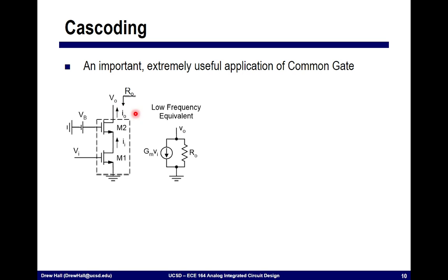Essentially we can take this amplifier, and we know M1 is inverting our input signal and generating relatively high gain. The current that's coming out of M1 is being buffered by M2. And here we're creating a much, much larger output impedance, or an effective output impedance Ro.